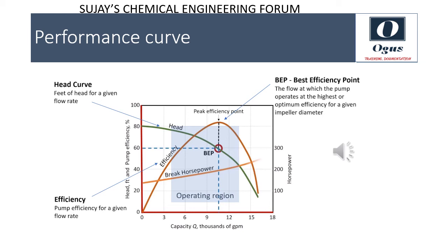This circular and irregular flow pattern is known as recirculation. The more flow is reduced, the greater the amount of recirculation within the impeller inlet. Once recirculation becomes excessive, it will result in increased vibration and pressure pulsations. Pump manufacturers make a determination, based on engineering analysis and experience, and establish the minimum flow that must be established to avoid excessive recirculation. This minimum flow point is called the minimum continuous stable flow.